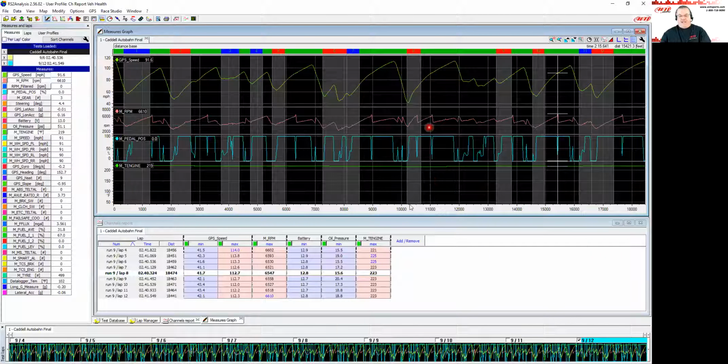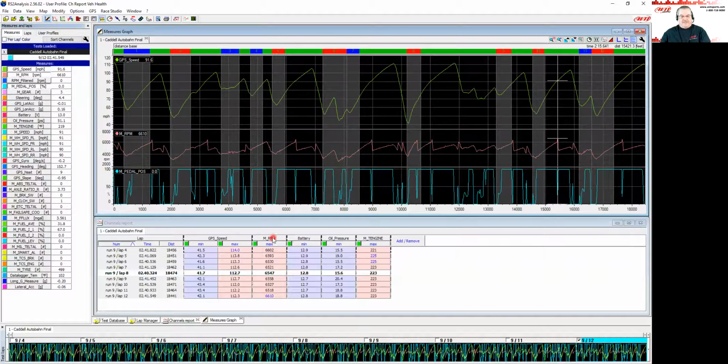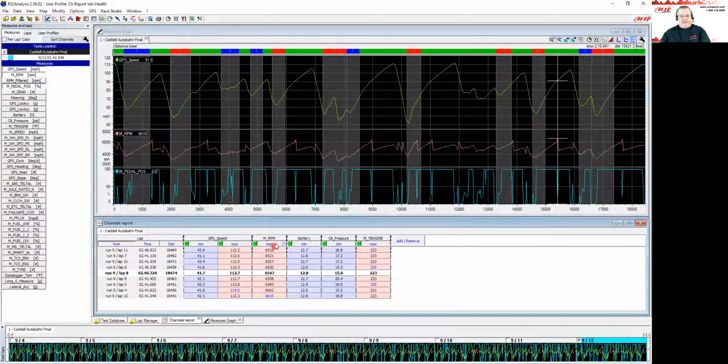Another thing that's kind of cool that you can do with this, let me turn off that engine channel, is by clicking on this column right here, you can sort ascending and descending these RPM values, and it changes the actual laps as well. The other thing you can do is click on this little colored bar. They're all so big and so close that the histograms don't look so different, but we can see if any of them jump out.